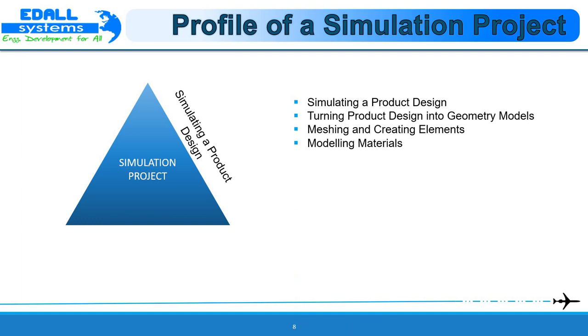Modeling material. The materials application is where you define the materials for your analysis model. A material model is a group of material properties that describe what your model is made up of, such as steel or a composite, and the attributes of that material, like stiffness, density, and so on. Once you define the material for your model, you will assign them to model regions.